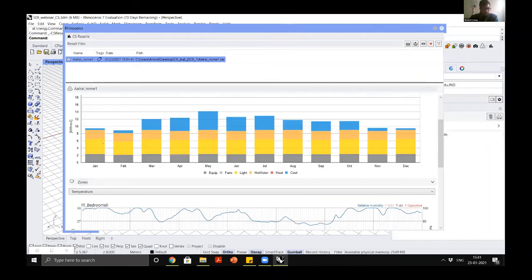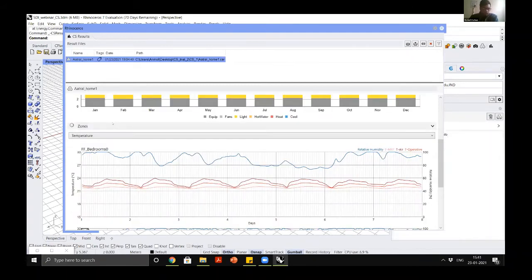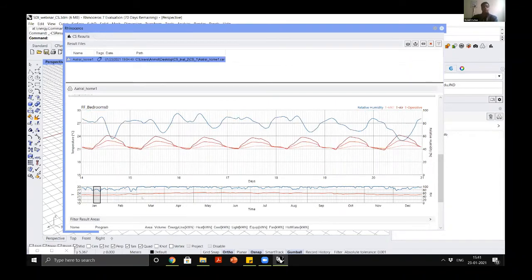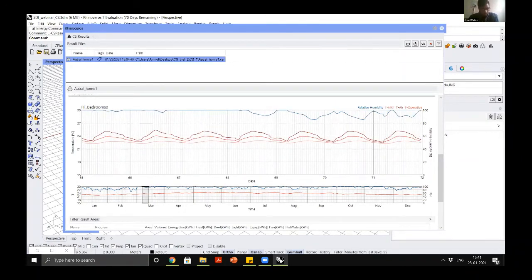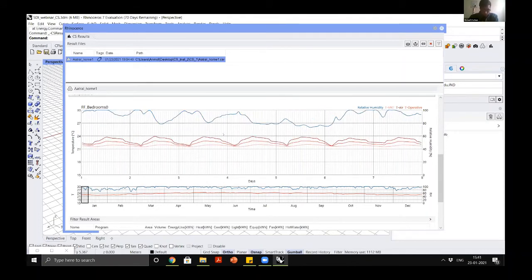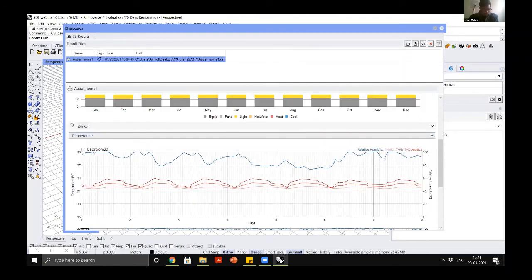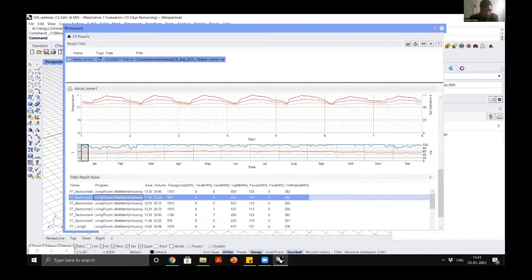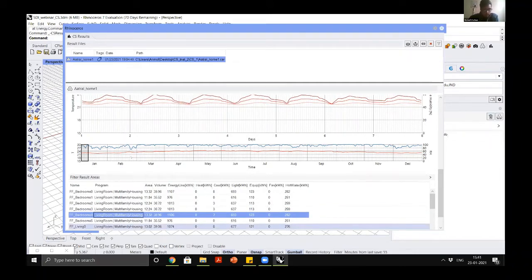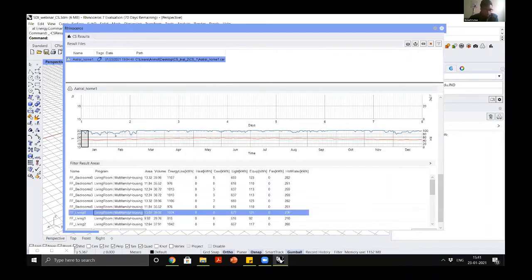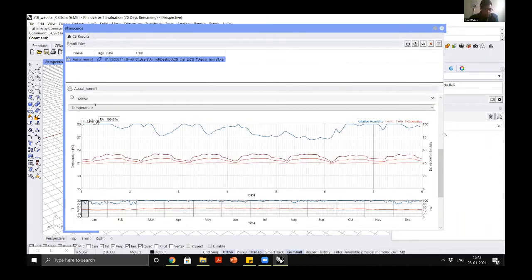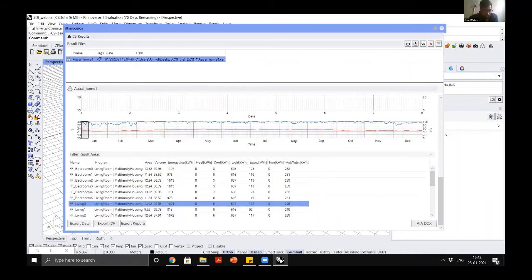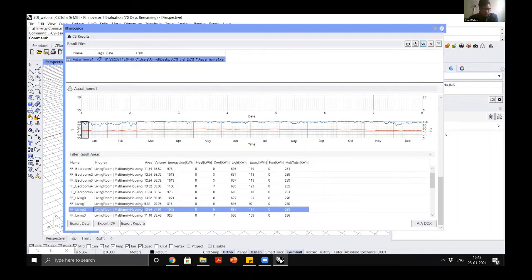On the building level, we get the energy use intensity. On zone levels, we were also looking at temperature. So we get an hourly plot of 8760 hours of the year, showing how the zone's temperatures are. So we can change the zone which we are looking at. We can select different zones and we can see their results. We can compare the results of different zones, and the same way we can select more simulation outputs. If we had, let's say, energy flows, but we did not simulate them. So these kinds of things can be done fairly easily with Climate Studio.